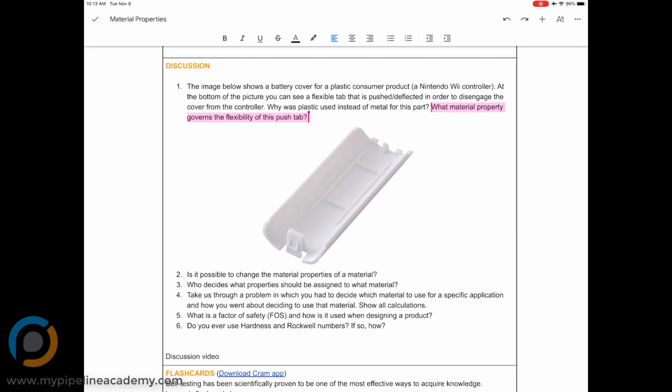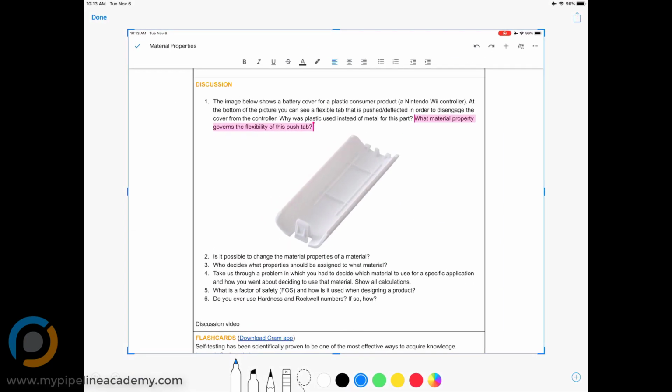That's right. Yeah, low enough so that it will flex without breaking and plastically deforming. Yep. Okay. Yeah. So that's the whole intent behind this feature right here, is that it flexes inwards. It's displaced in order to disengage it from the rest of the remote control. And then when you release that tab, it just springs back into its original shape because it has not plastically deformed.